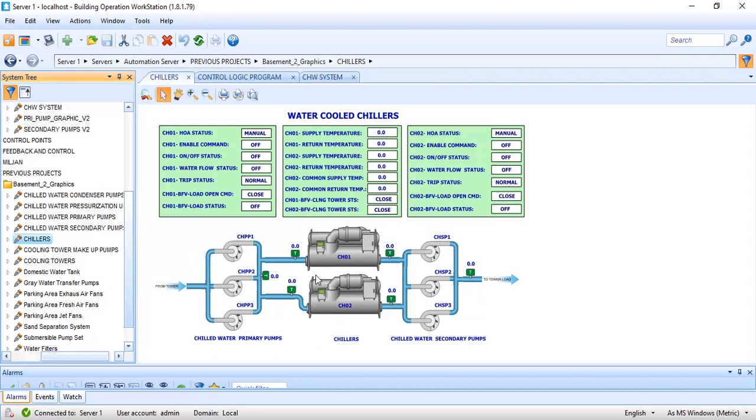This is a system, meaning there will be primary pumps. Then we have secondary pumps. We have these butterfly valves with valve actuators. So this one will be the one that you are going to write the control for. Now we also have to monitor some parameters like the entering chilled water temperature and the leaving chilled water temperature.